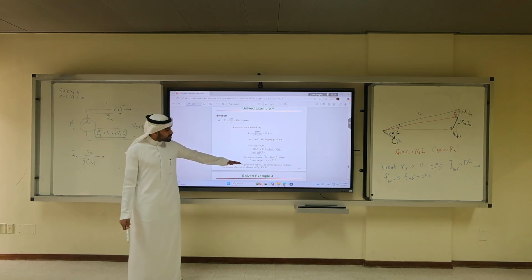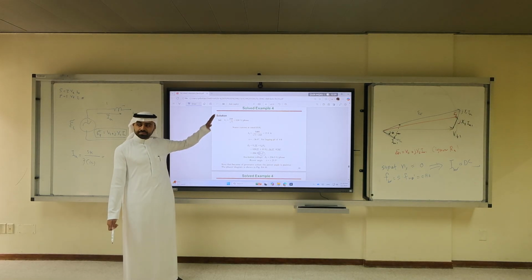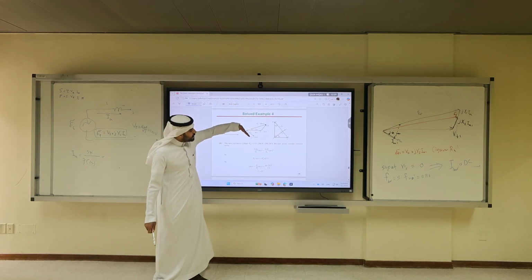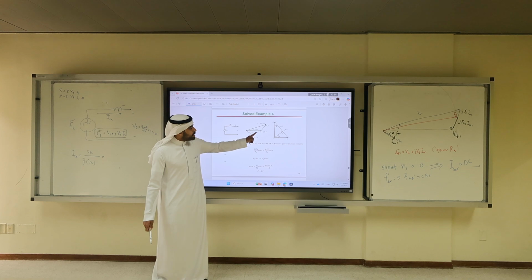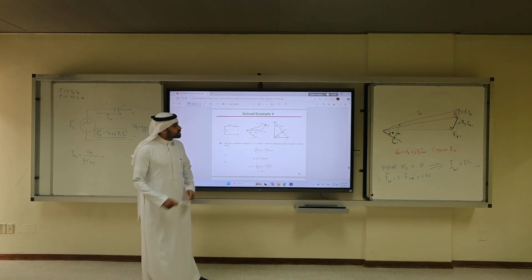So this is, you can solve it with your knowledge in 360. Clear? This is the phasor diagram: Vt, Ia, jIaXs. This is your EF, delta is positive, check, we're at the generator mode. Okay?